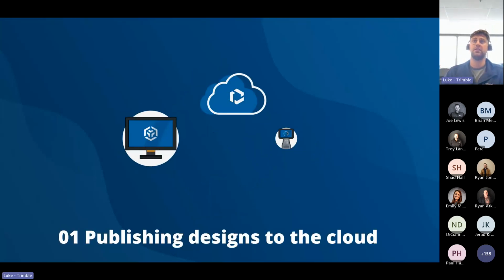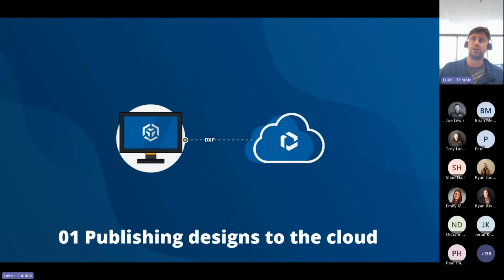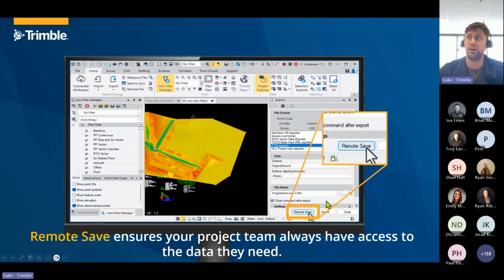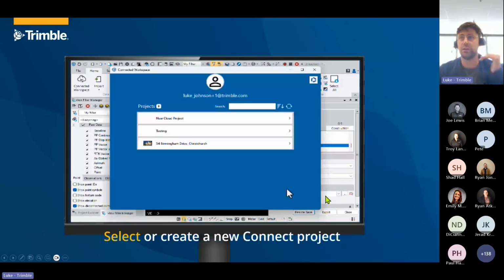So that first step is actually taking your designs from your office program and publishing them to the cloud. If you use TBC, I think it may have been the latest release of TBC, in the export form, there is now a remote save button. And that button lets you export your files directly to Trimble Connect.